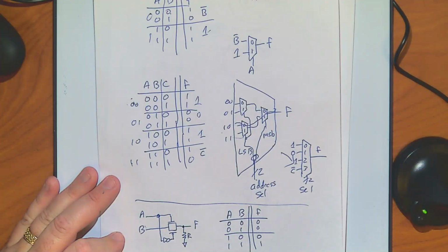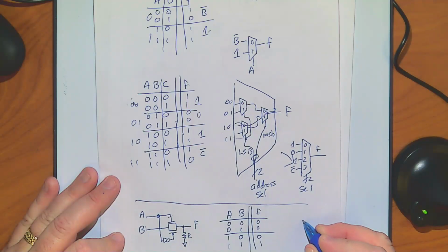And if you notice, when I was doing the design analysis, I broke it up the same way. This is also very popular for XORs or equivalent circuits because you can break them up into these types of patterns. But basically, that's the trick to how all of these work. If I wanted to make an OR, you can imagine an OR looks like, I drew that backwards, 0, 1, 1, 1.